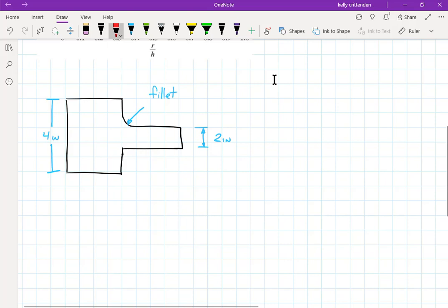So we've been calculating basically this kind of average stress in the bulk of the material, but around these sharp corners, there's a really high stress concentration there. And so there's a really high stress there, compared to anywhere else in the material, and so things start to fail, particularly when things are in fatigue, so they're loaded and unloaded and loaded and unloaded. That'll be really bad for them.